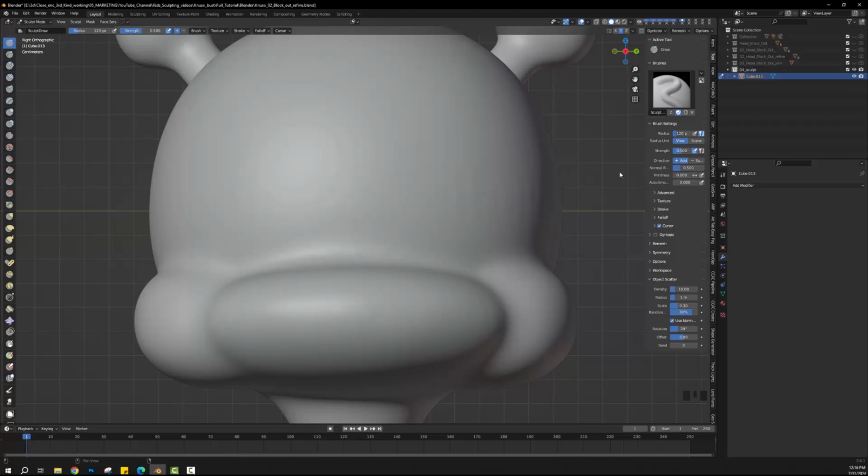So right now what we want to do is we want to push in to the actual geometry to create the eyes. So make sure you've saved your file. And right now, if we do, it's going to bring the geometry out. It's going to add. So I'm going to hit Control Z, where you can go up here to edit, undo.